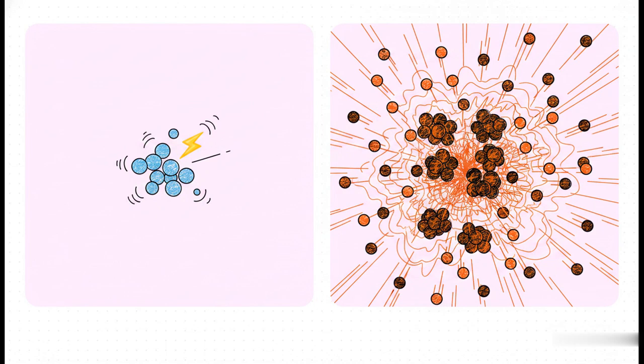And once again, we're looking at a paradox. Sure, on one hand, that extra chaotic kinetic energy can give you a little assist in tearing apart loosely bound clumps of pigment, but honestly, it mostly acts as a total saboteur. The collision frequency goes absolutely through the roof. Those perfectly separated particles are moving so fast that they slam into each other, bust through their protective barriers, and just fuse right back together. You are literally watching your hard work undo itself because the system is just too hot and too chaotic.